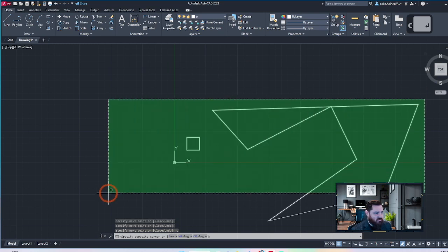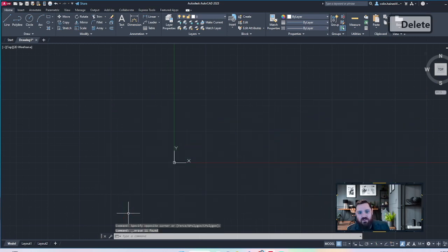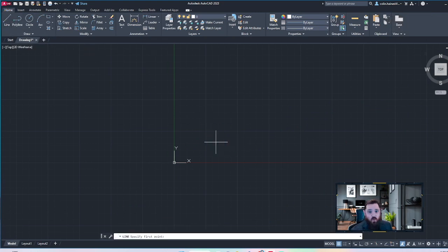And let's go ahead and get rid of all that stuff because that's not of much use to us. And then let's look at another way we can make lines. So what we just typed in were called absolute coordinates. And it's weird. I've seen AutoCAD defaulted to different things, just depending on who's using it. I don't know how it determines what the default is. But sometimes you default to relative coordinates and sometimes you default to absolute coordinates. And that may seem like jargon right now, but I will try to explain it.